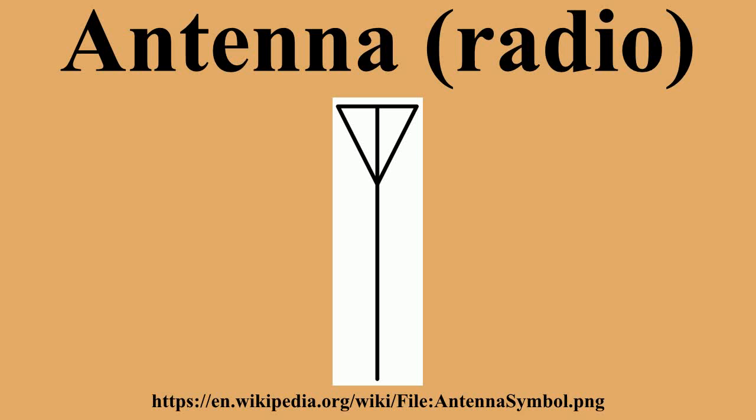Antenna gain, in this instance, describes the concentration of radiated power into a particular solid angle of space, as opposed to the spherically uniform radiation of the ideal radiator. The increased power in the desired direction is at the expense of that in the undesired directions. Power is conserved, and there is no net power increase over that delivered from the power source.